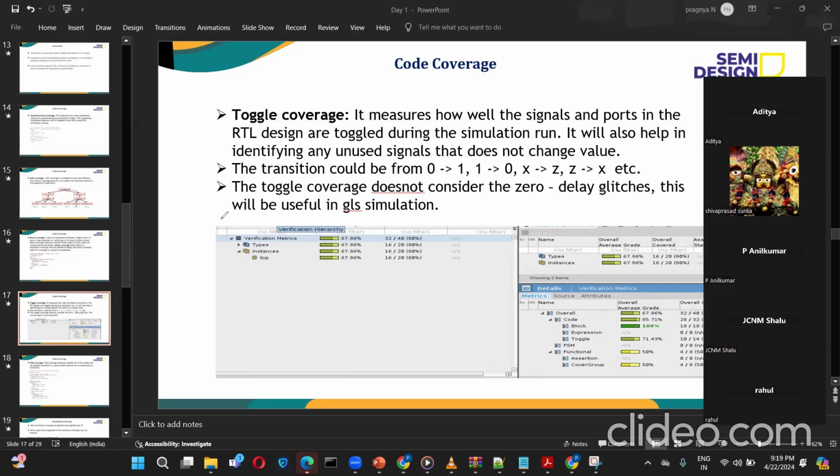We are only using the 7-bit addressing mode. So if you are using only the 7-bit addressing mode, the 10-bit addressing mode variable will not toggle, right? So you have to understand that we are not using this feature. That's why this is not getting toggled. So you have to check with the designer whether the conclusion you have reached is right or not.